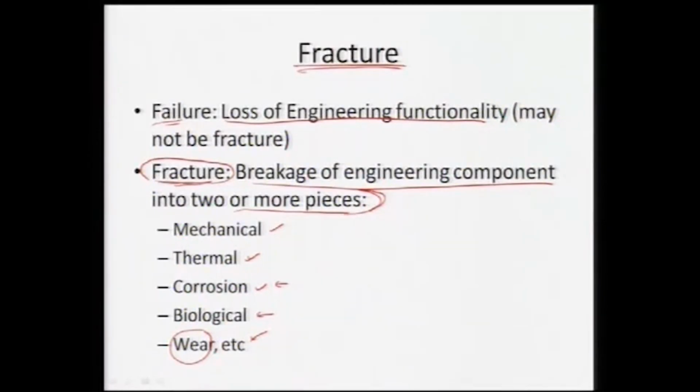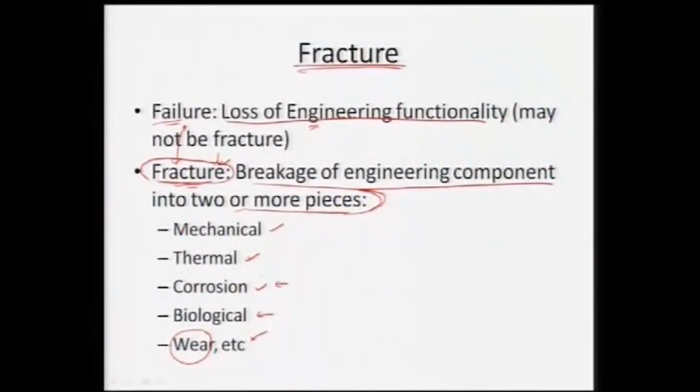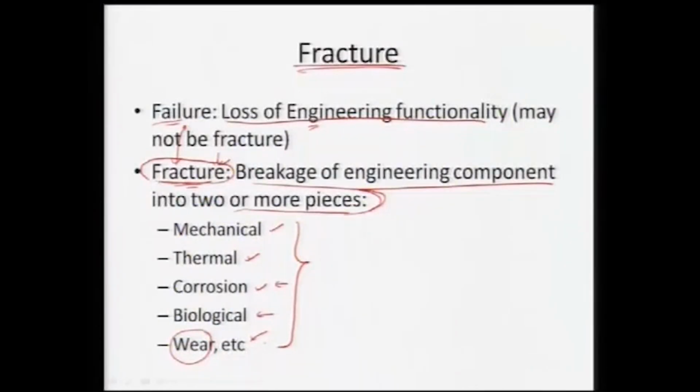So, we can see the fracture is very different from failure, because failure is a loss of functionality, it may not result in fracture. Fracture is the final stage, like even after failure the component can fragment, that is the next stage of failure. Fracture definitely means failure, but failure does not always mean fracture, and fracture can be induced by various input variables such as mechanical shock or thermal shock or corrosion of the material. It can be biological damage to the material, it can be wearing of the material, and there can be many other factors as well. A combination of these or more can also induce the fracture.